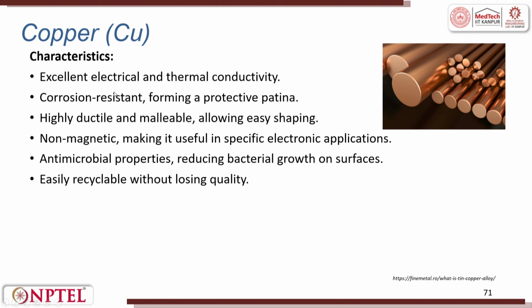Let us move to the other alloy, which is copper based alloy. Copper based alloy always gives excellent electrical conductivity, which is generally not so high with aluminum. It has corrosion resistance, forms a protective patina on top of it, highly ductile and malleable, easy to shape. Copper is easy to shape.